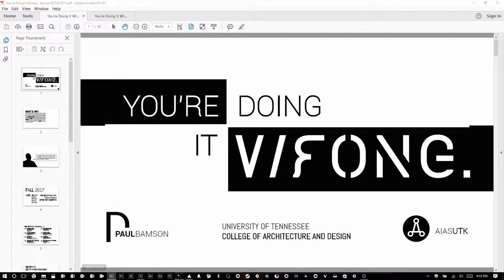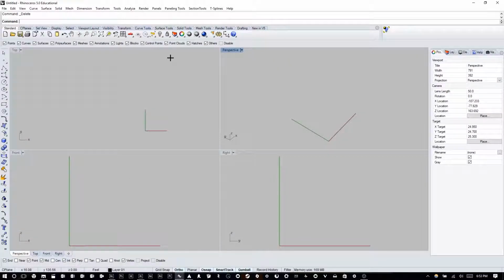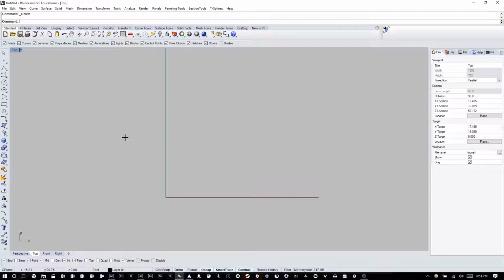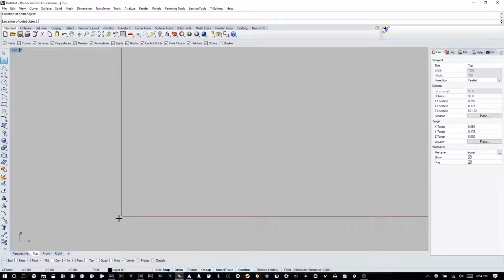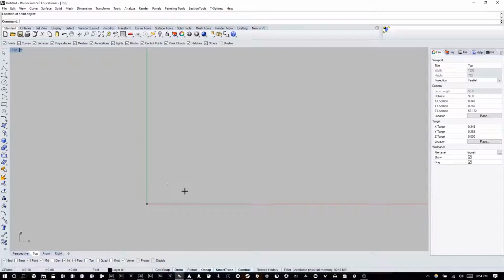We're going to start here with some simple Rhino geometry. I'm going to create the 3 basic Rhino forms that define the NURBS modeling that it does, and some interesting things you can do with them. So I'm going to pop in the top view here, and I'm just going to create a point, and there are 2 ways to create a point, either by clicking the point command in the standard tool set and placing it, or typing in point and placing the point that way. Either way works just fine for what you want to accomplish.